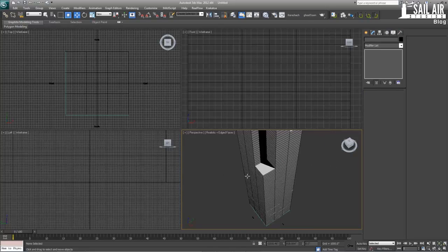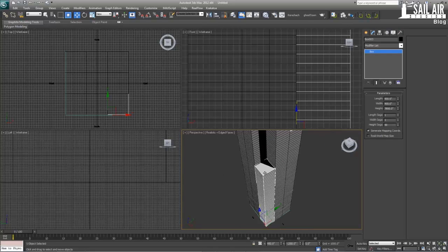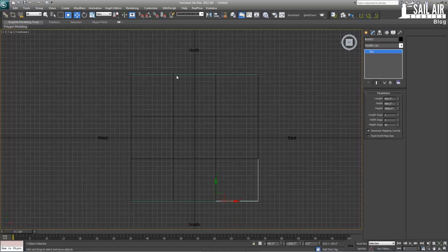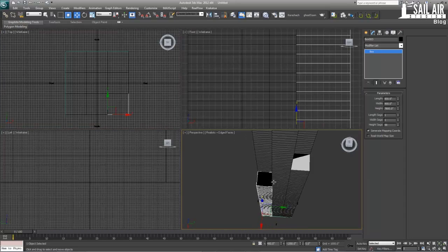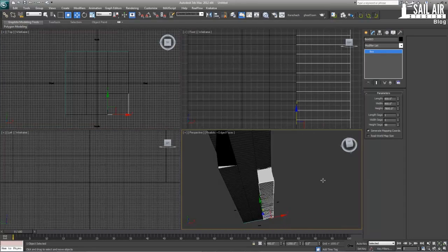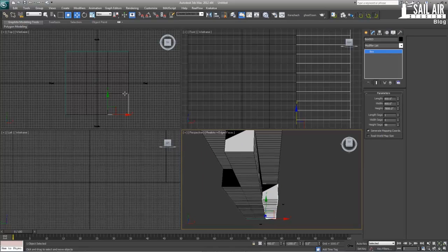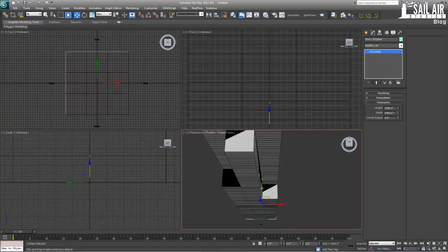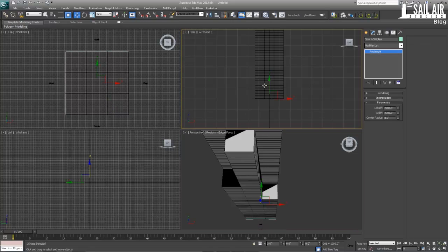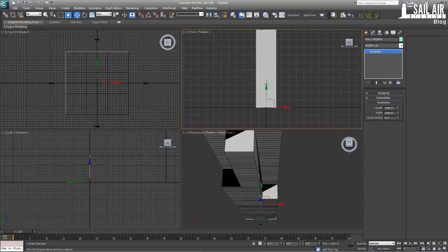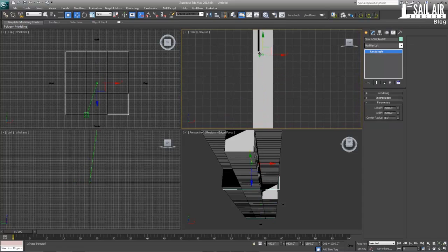Next, what we know is that our southeast and our northwest towers stop. So trying to just set it up to be the same, there we go, same as my top view. So we're going to have to create a spline that goes around here like this. So how we do that is we literally just copy and paste this spline up to whatever floor it is, and I'm just going to hit F3 so I can see the edges of it. Yeah, I know it's right there.